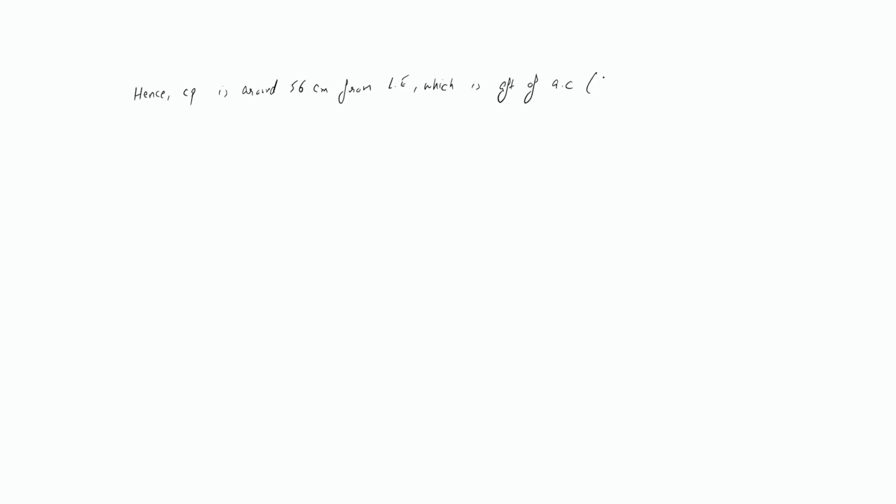Where was the aerodynamic center? Quarter chord point, right? So 37.5 centimeters from the leading edge, which is as expected for a cambered airfoil.